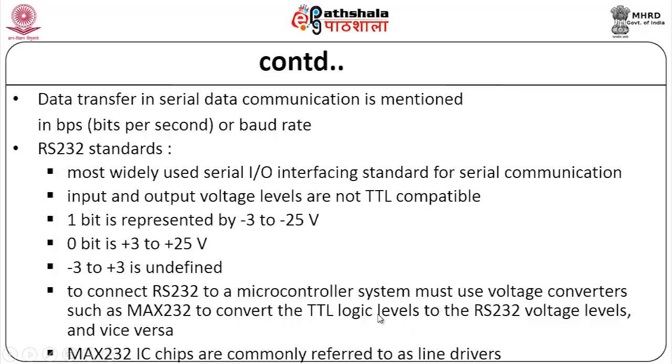TTL logic supports only lesser voltage levels. So when I want to interface a PC's serial interface with a microcontroller, I need to make the RS-232 compatible with the microcontroller, that means RS-232 is converted into TTL level.